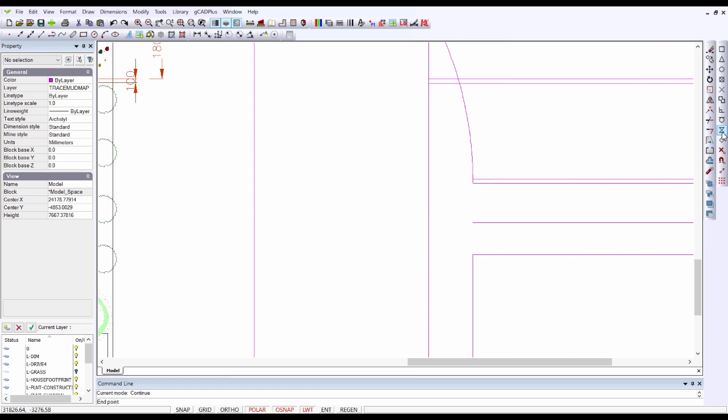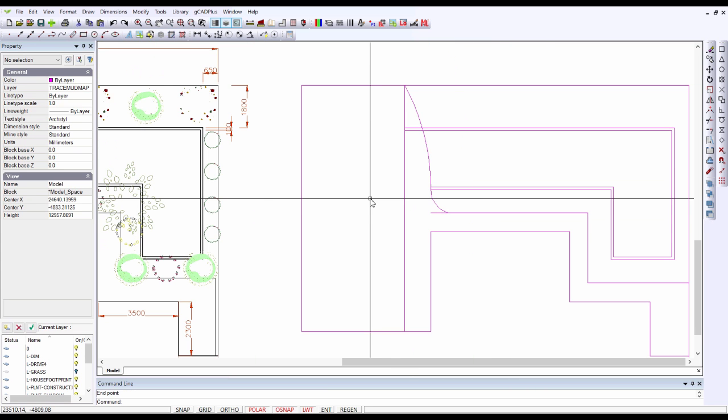And for that I'm going to use the nearest option on OSnap. So can you see now, because nearest is on, it's going to anchor itself on that line, and so I can come along through here and get the sort of shape I want. I'd be inclined to click at about the point where the arc is tangential to the line. We can go endpoint, and I'm doing this by eye, and I think that will satisfy me.